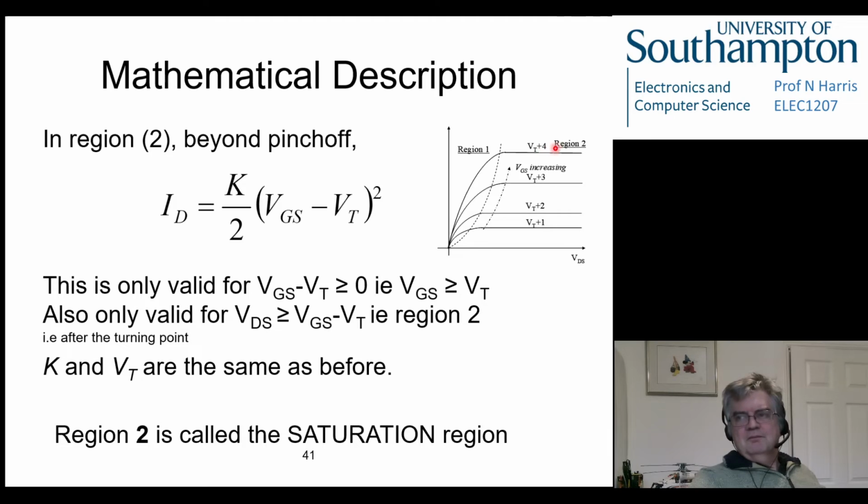So for this field effect transistor, we've got the saturation region here, the flat region, and then we've got the, what was it called, the active or linear region here, wasn't it? So this is the linear region for a FET, and it's called saturation in a bipolar, and this is the saturation region for a FET, which is called the active region in the bipolar. So these kind of things make good exam questions. They're kind of definitions.